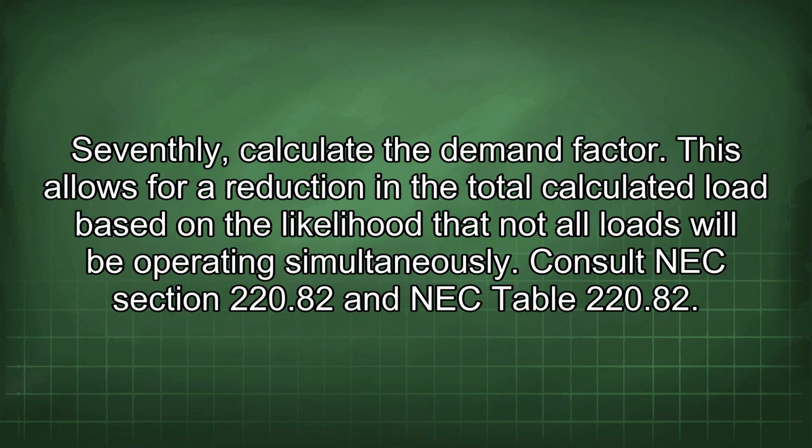Seventhly, calculate the demand factor. This allows for a reduction in the total calculated load based on the likelihood that not all loads will be operating simultaneously. Consult NEC Section 220.82 and NEC Table 220.82.